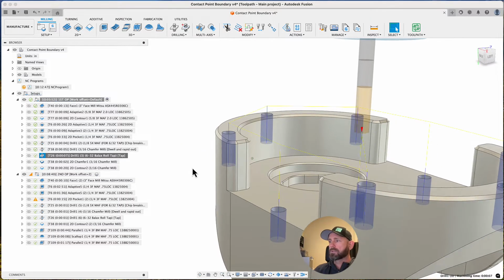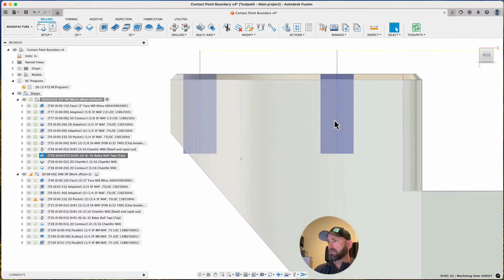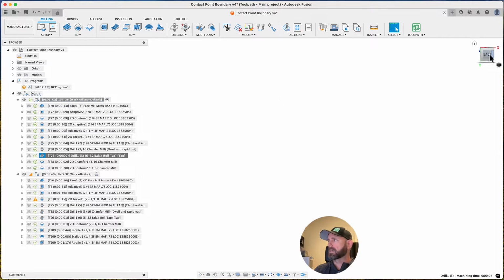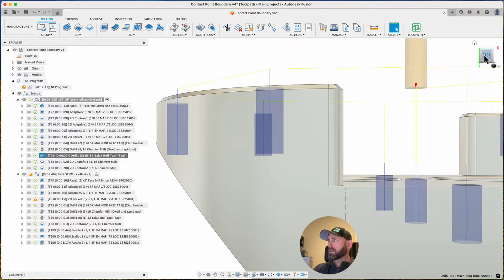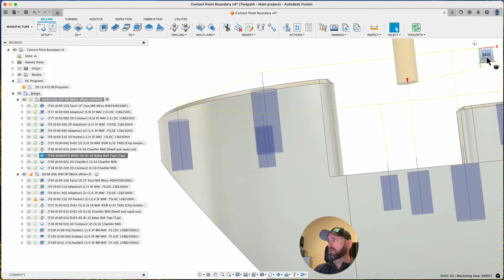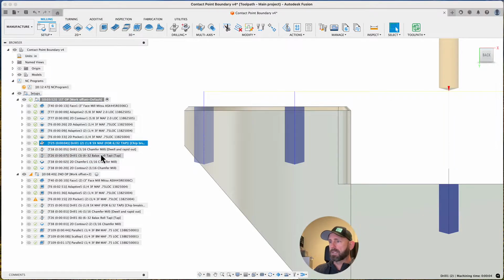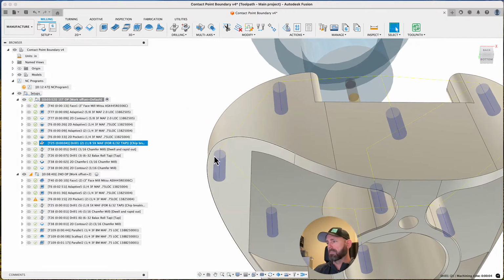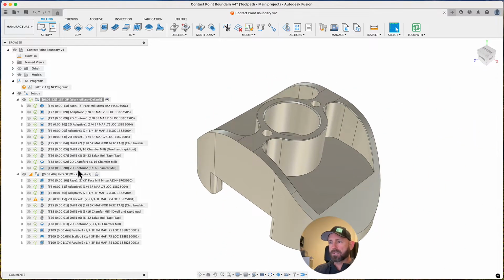requirement. So now what that does is, well, it's going to create a breakthrough there, so I probably want to rethink that, to be honest. Now what we want to do is we can look at the drill. So the drill and the tap kind of satisfy each other, right? So we'll have to go back and look at the thread depth and all that and make sure we don't get that breakthrough, but we'll push on now because that's just a little nugget I was trying to drop on you.